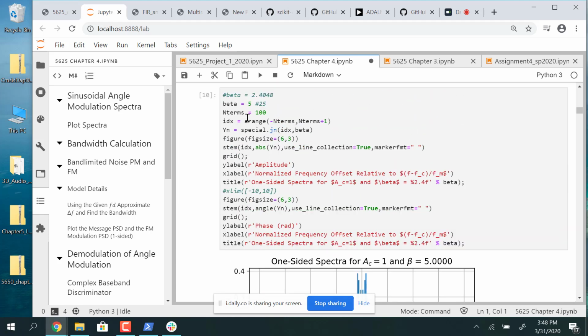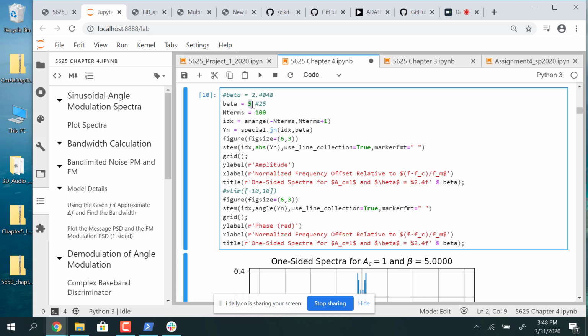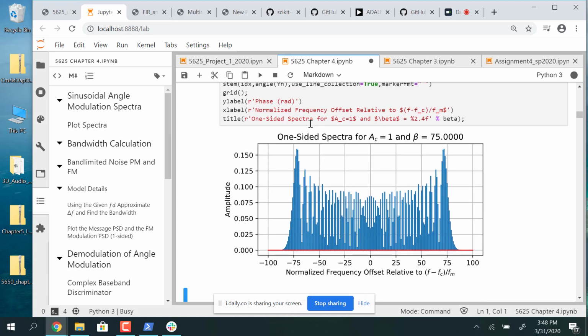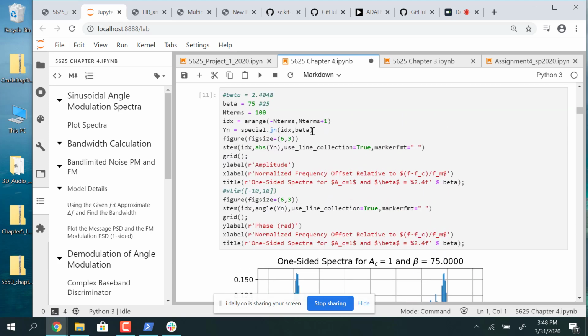And let's just go to the value that FM broadcasting uses. It uses a deviation constant of around 75. So it has a peak deviation that goes 75 kilohertz below and 75 kilohertz above the carrier frequency. But that spreads the signal out slightly wider than that. So a single sinusoidal tone would create a spectrum that looks something like this if its deviation constant was 75.